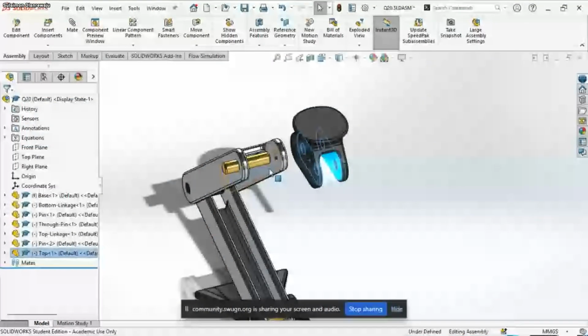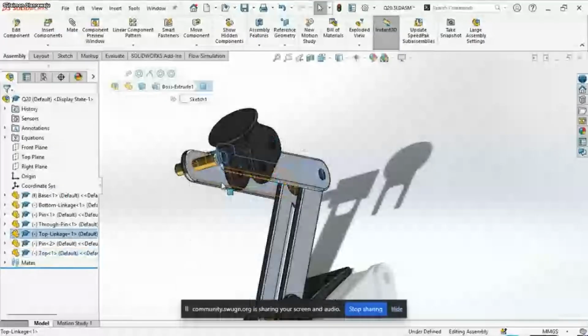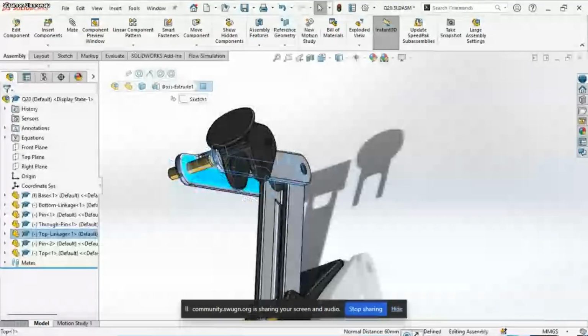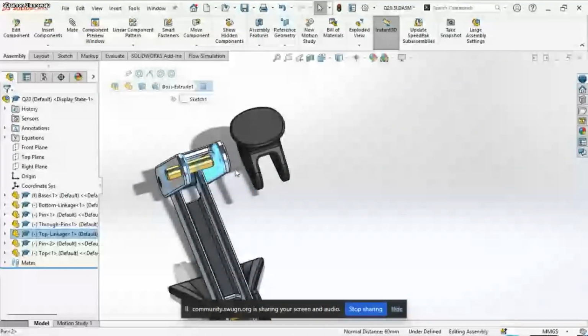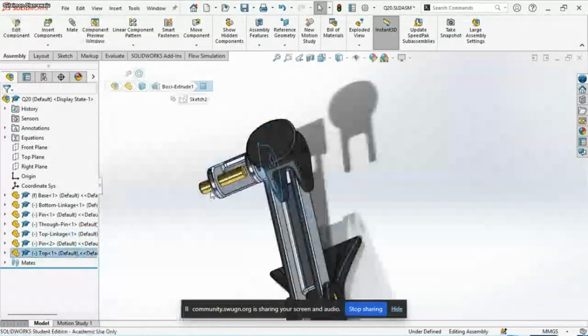While for this, holding your control instead of clicking on your measurements, the distance between those two faces I just selected, this and this, it will appear here, 60. That shows that the width of this one is larger than the width of this top part. So that means this one goes inside this. That means you are making this face coincident with this face.